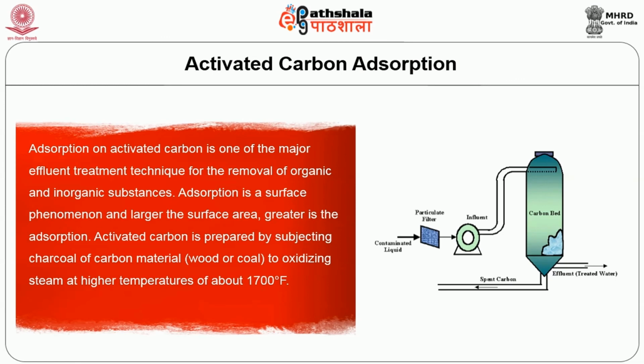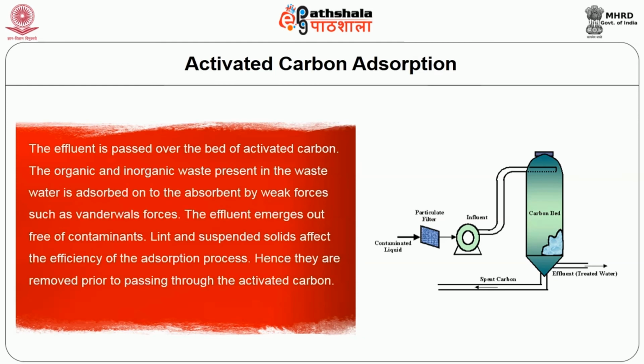Activated carbon adsorption. Adsorption on activated carbon is one of the major effluent treatment techniques for the removal of organic and inorganic substances. Adsorption is a surface phenomenon, and the larger the surface area, the greater is the adsorption. Activated carbon is prepared by subjecting charcoal of carbon material to oxidizing steam at higher temperatures of about 1700 degrees Fahrenheit. The effluent is passed over the bed of activated carbon.